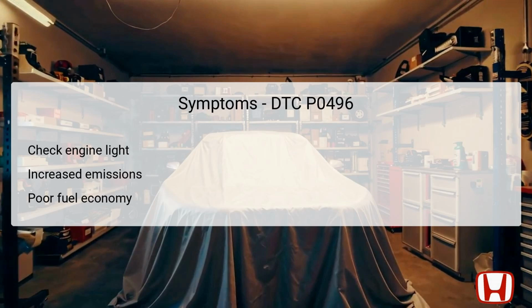Increased emissions may result due to improper management of fuel vapors, leading to potential failure in emissions testing or regulatory compliance. Moreover, drivers might experience poor fuel economy as the engine struggles to process excessive vapor flow, which impacts combustion efficiency. In some cases, the engine may exhibit rough idling or other performance inconsistencies arising from the disrupted air-fuel mixture. It is vital for owners to diagnose these symptoms swiftly to avoid any prolonged damage to the engine or emissions control system.